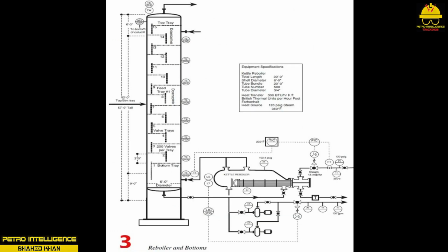10. Set hot oil TIC to required set point. Monitor hot oil flow rate and temperature trends. 11. Set kettle reboiler to 50% and put in auto. 12. Line up kettle reboiler bottoms pump to tank farm. Check valve lineup. 13. Set kettle reboiler TIC to required set point, auto. The TIC is cascaded to the FIC. 14. Set kettle reboiler FIC to required set point, auto. Put in CASC shortly after unit startup and feed is flowing.